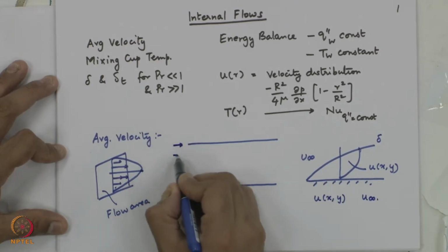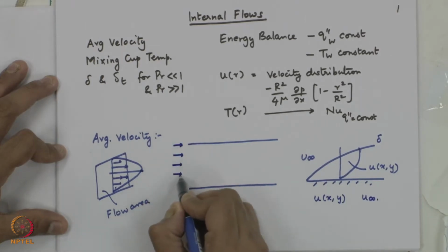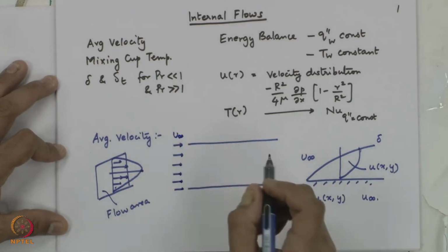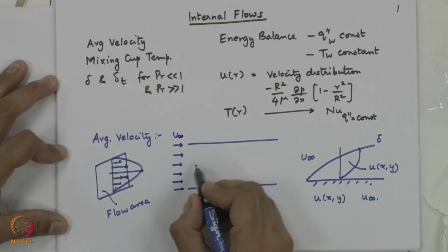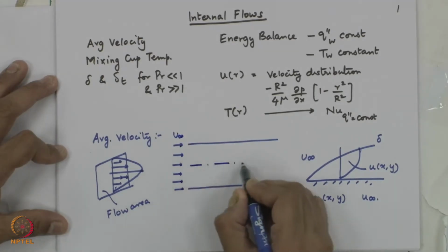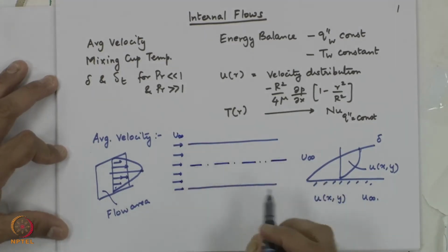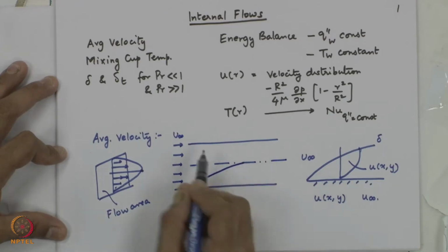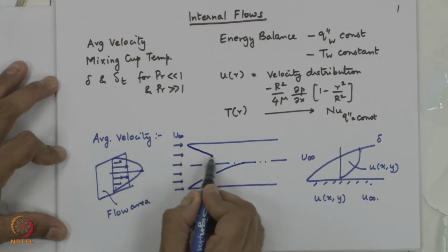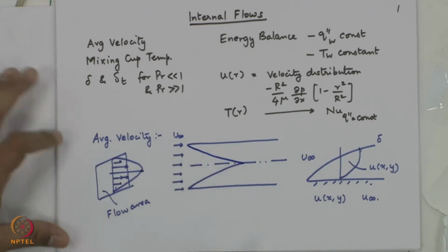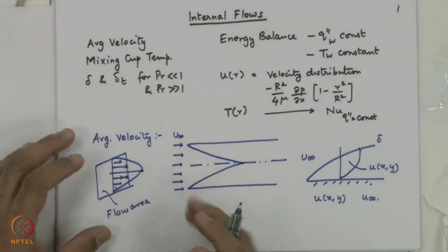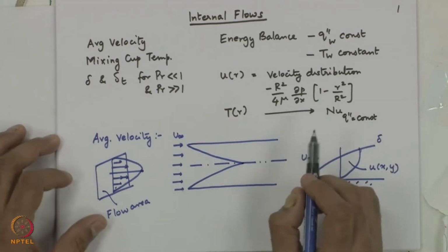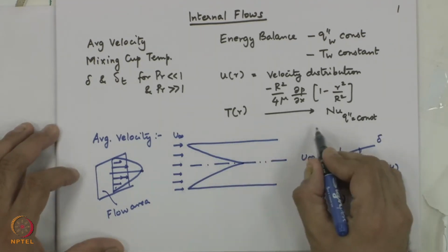Here in internal flow, if you are talking of say a circular pipe, or even flow through parallel plates, what is going to happen is the following. You would have a boundary layer developing all around the circumference of the pipe, because unlike external flow, you have another boundary over which the boundary layer develops, another solid surface.